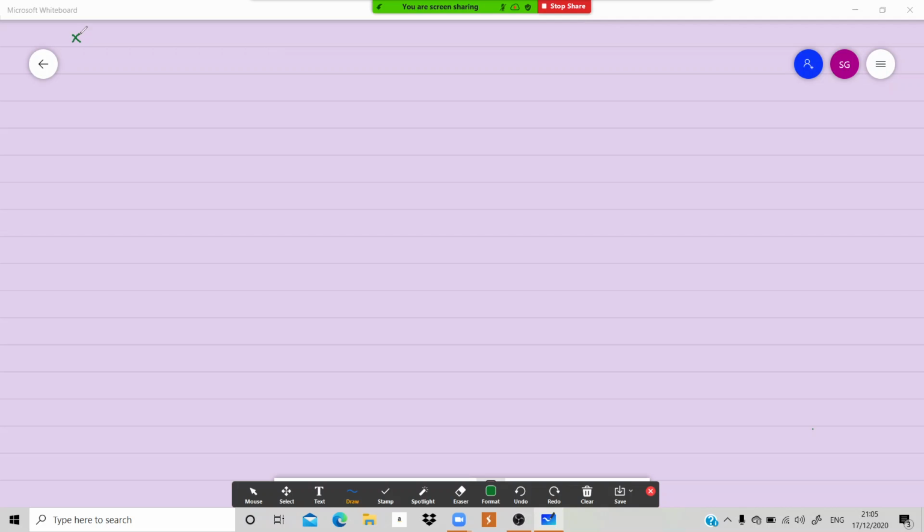So X of Z when you are writing, that means you are signaling Z domain, that is Z transform of X of t, where t is the continuous function, correct? Then that is equal to summation of k equal to 0 to infinity x of k z raised to minus k. Okay, so this is the definition of Z transform.